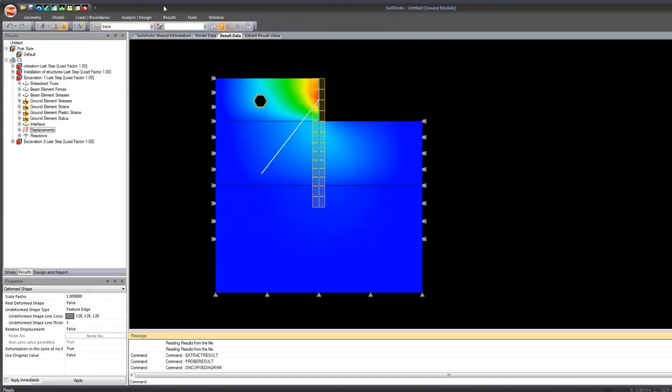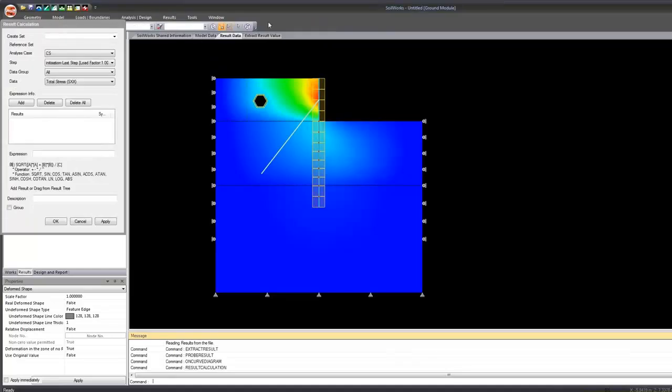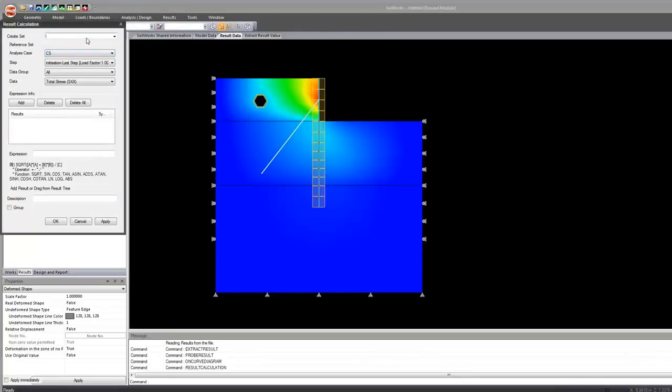And finally we have the effects function. Let's suppose you want to create any set A, and what you want to consider is only the horizontal displacement. So click add. It will be added as A, and similarly we have the vertical displacement, click add. So we have two sets A and B. Now you want to create a set where you just want to see A plus B. So this is your particular area of concern. So just click OK.